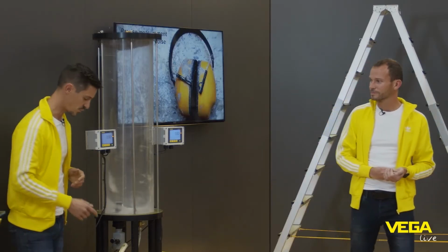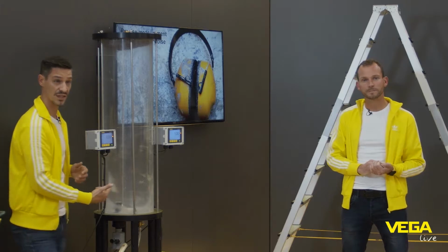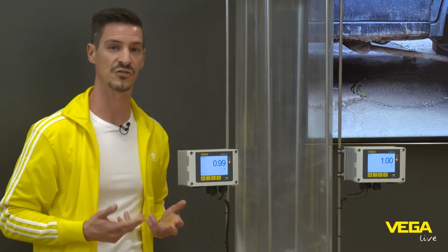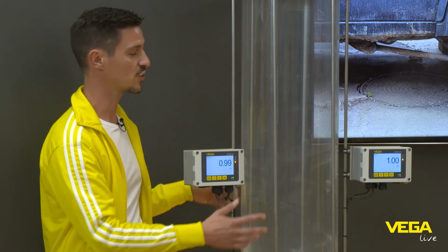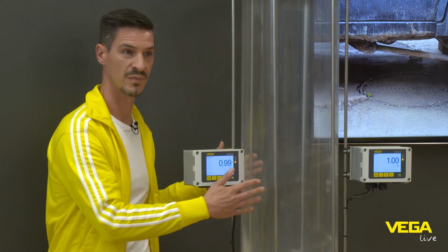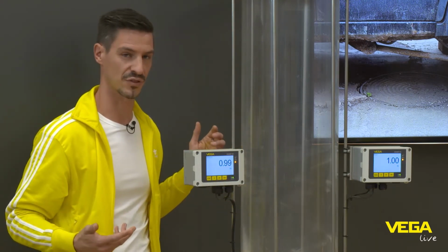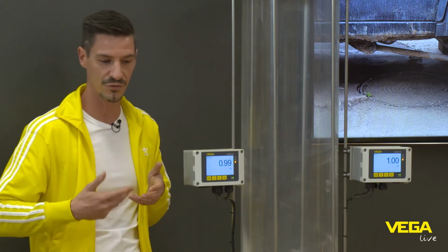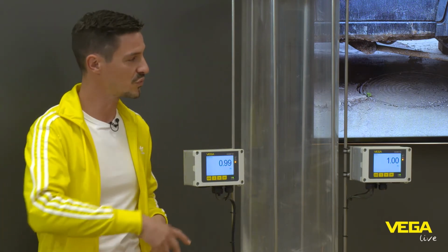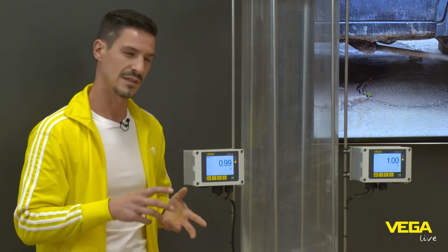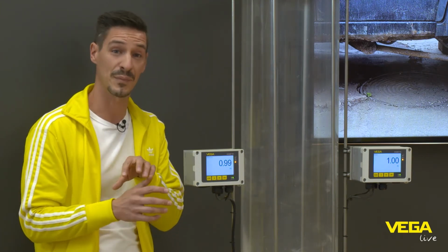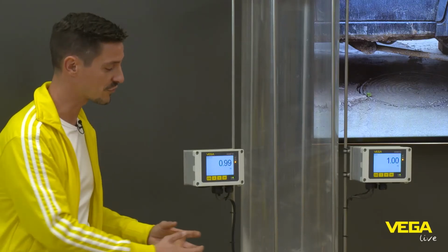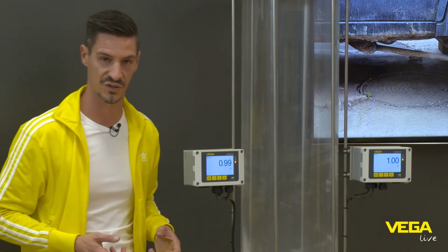We are using pressured air to generate this little twister inside this tube. And this pressured air also has an influence on the ultrasonic measurement. With the pressured air, we generate overpressure within this tube. This normally supports ultrasonic. The more air is inside this tube, the better it is for the ultrasonic wave to move through the air. Let's look at the opposite. There are some applications within the bulk solid industry where you take material out of the tube by a pneumatic conveyor system, for example.